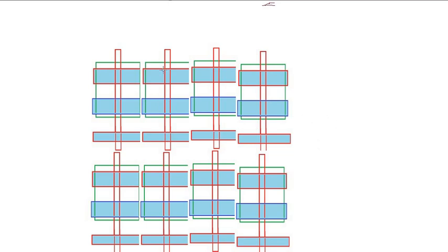Okay, you're aligning them, but unless it's the same connection, you will leave it as is. But if it's a separate connection over here, you will be using a cut layer, for example, here. If these two connections are the same like this, you can leave it as is. You don't have to put a cut layer. Now, if these two devices are separate and you want to cut the connection over here, then you need to draw a cut layer. Generally, cut layers are drawn at the ends of the device.